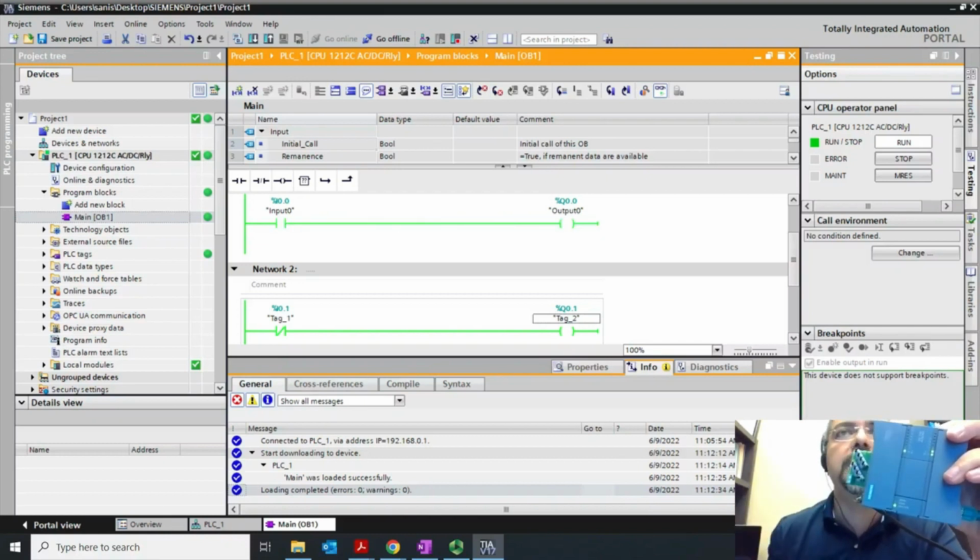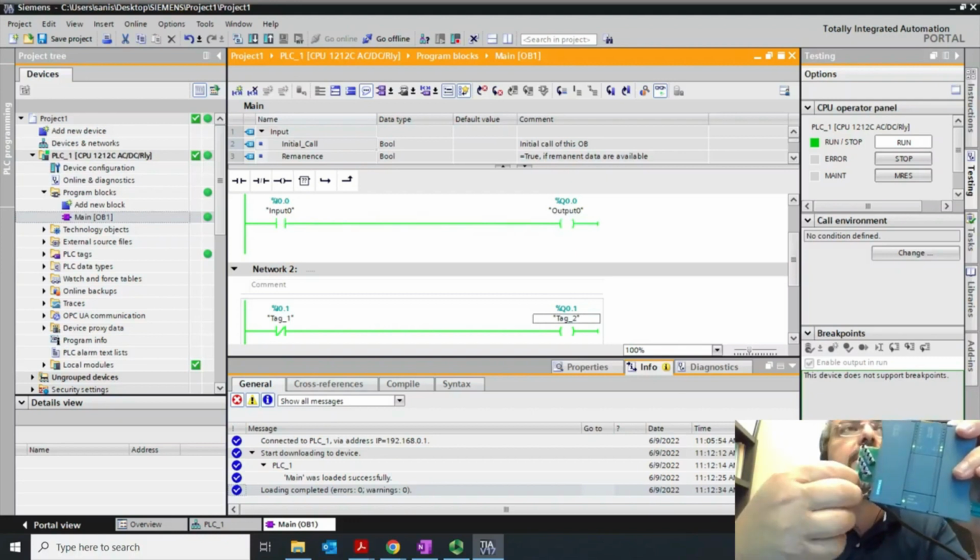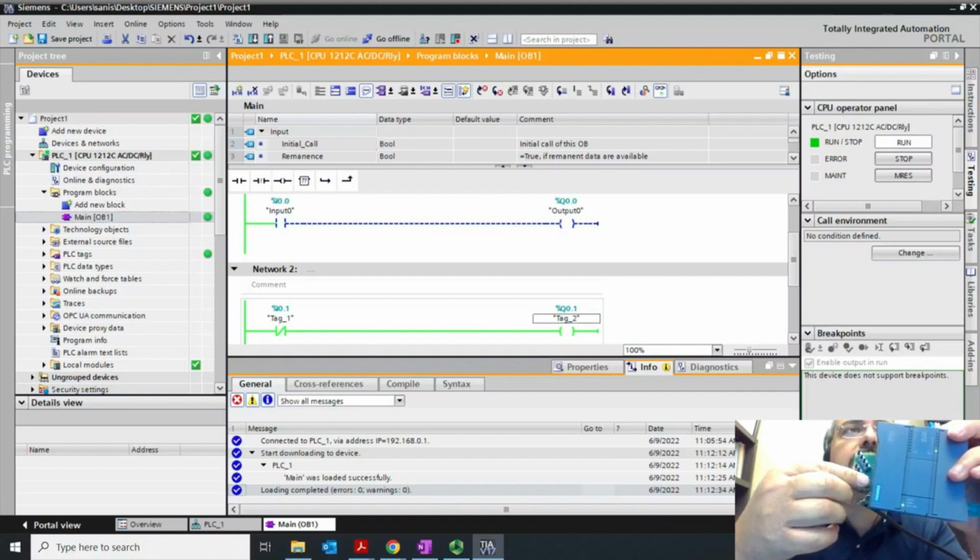And even you could see here in the simulation what's happening, right? So take a look at the first ladder that we have. Right now this is 1. So normally closed, normally open. Whenever it's 0, it should be open and the output is 0. You see it on the simulation and also you see it in reality, right? So same for these guys. I don't know, maybe I put these off and just try to work with the second one.